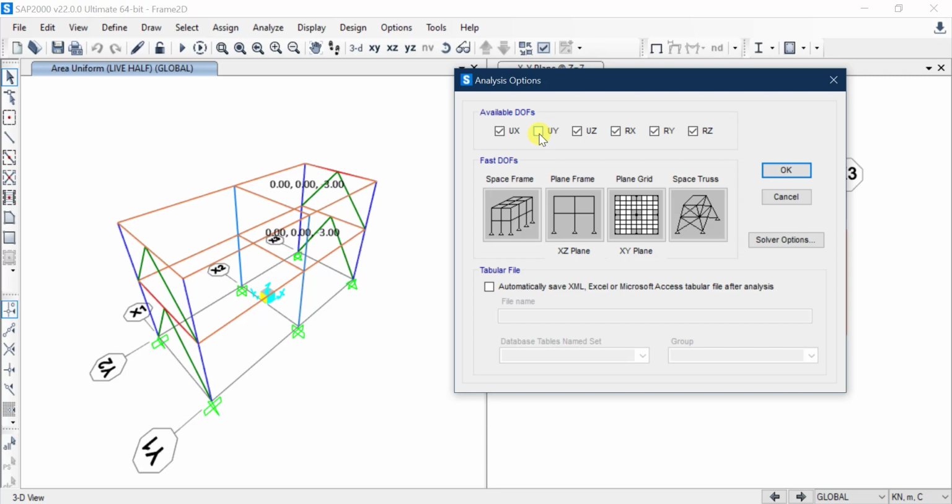Well, in theory, and also practically, if you have a very large structure, like a high-rise building that's much, much bigger than this one that we are analyzing, when you remove some degrees of freedom, the stiffness matrix becomes smaller, and of course, solving a smaller system of equations with smaller matrices is much faster.